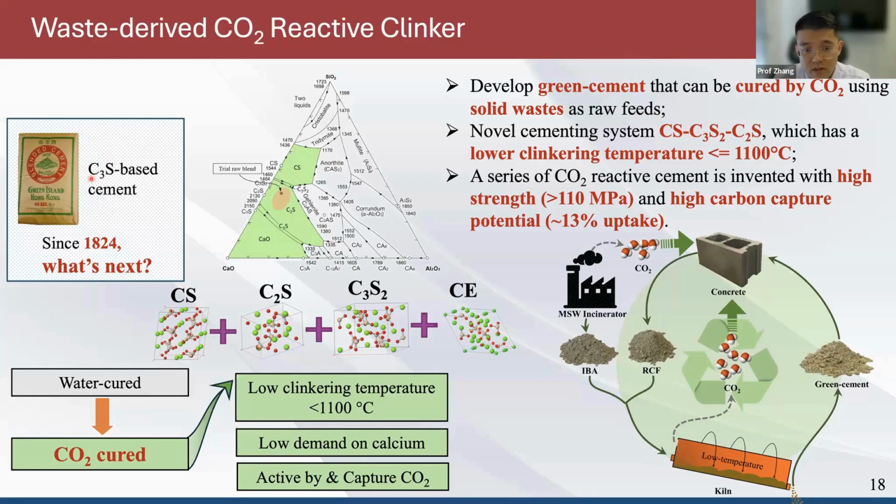But we have a phase with lower demand on calcium, so consequently we reduce the CO2 emission from that aspect as well. Not to mention that all those phases have a strong reactivity to CO2. So we developed a series of green cement that can be cured by CO2 using solid waste as raw feeds. This cementing system can achieve a very high strength, over 110 MPa, and a high carbon capture potential, 13% uptake. This number means 100 grams of our material can permanently sequester 13 grams of CO2.